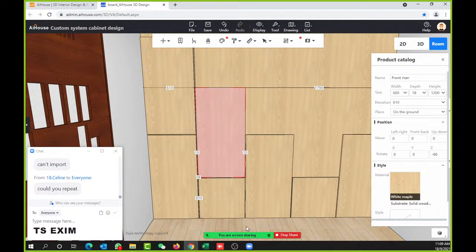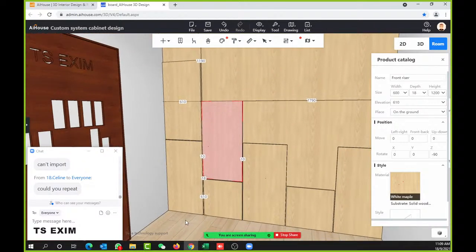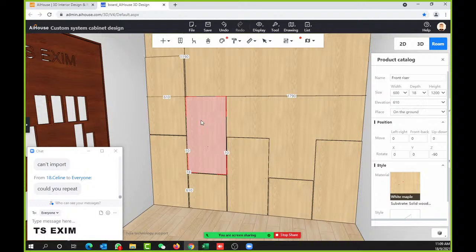Okay, time's up. So follow up with this banner also here. We click on this one, Ctrl V. This time I add only, because the elevation is correct. I add a 10 mm gap, and add another 600 banner. Then I add one more 10 mm gap.